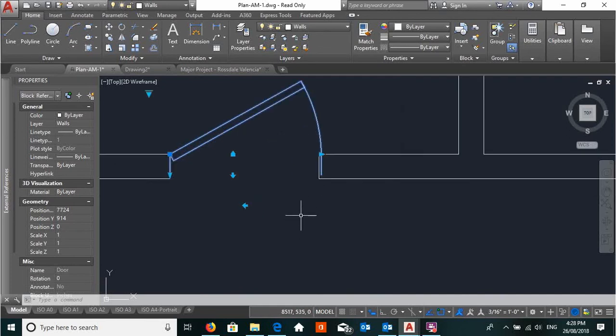You can see that this door swing has no outer frame. It's literally just a swing door. So preferably you would create that and maybe explode this item, add that, and then save it as a new block that you can keep for your reference for your drawings.